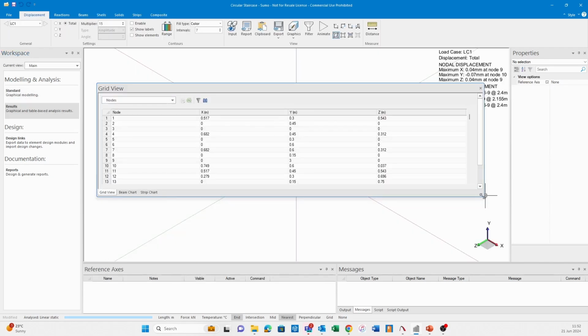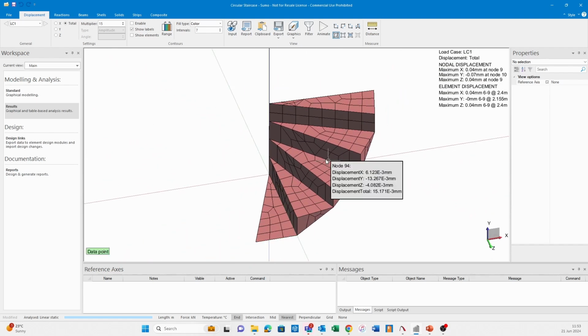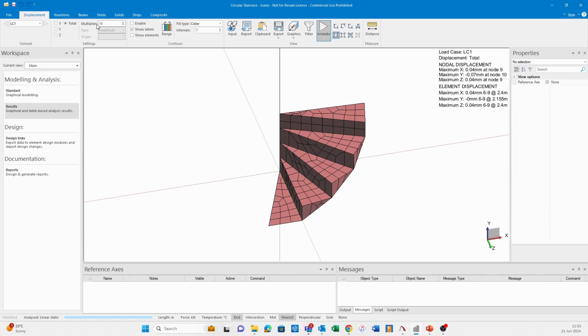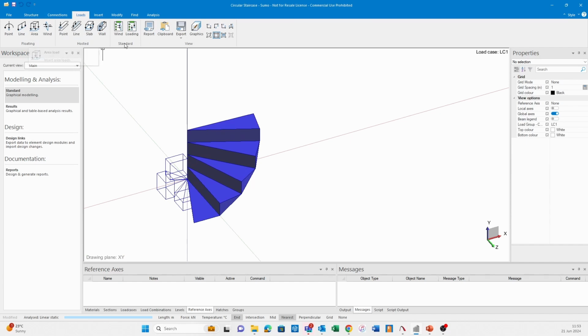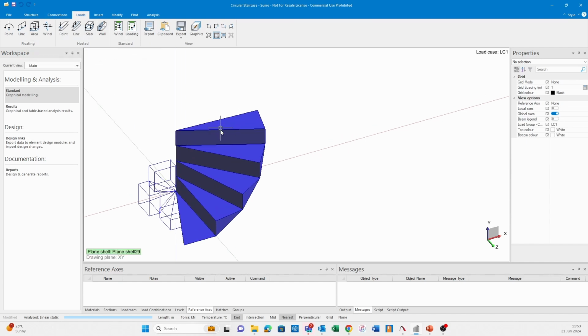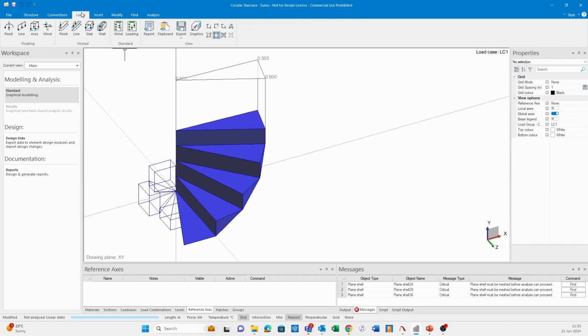All right, so just going to get this grid view out of the way quickly. And this is what we've got actually, which is really cool. So there's not a lot going on here. So let me actually go back. We put on some area loads there. So a slab load won't work here because it won't snap. So I'm just going to put on some area loads, 1 kilonewton. I guess we can even make that 0.5.